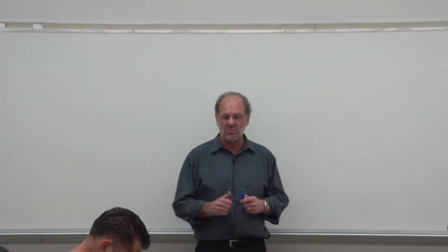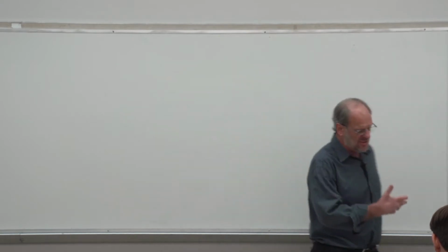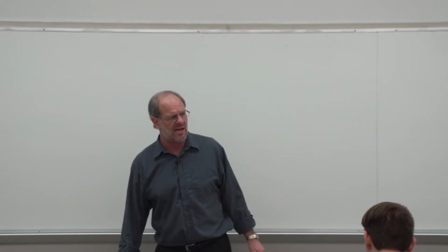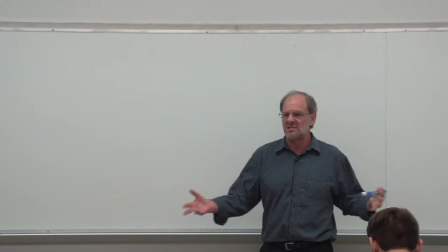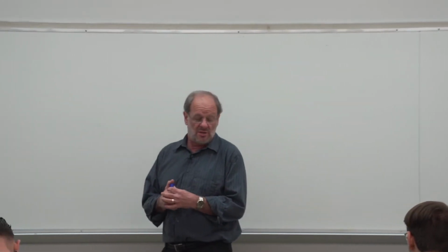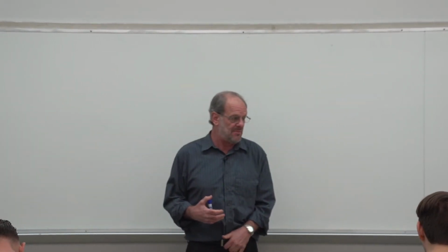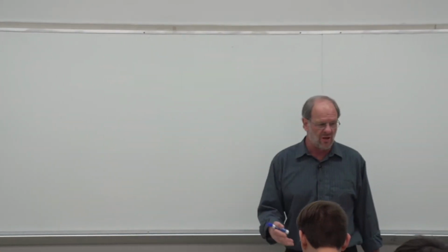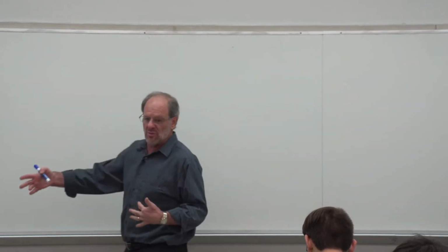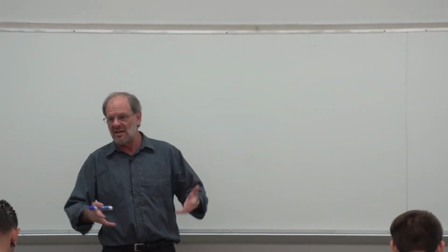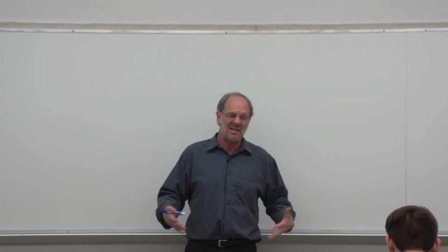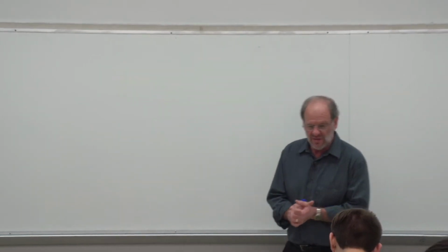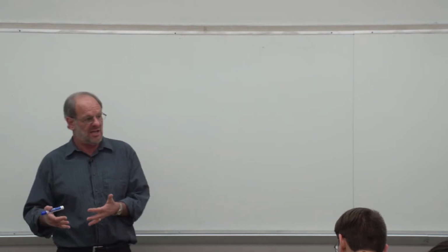Now, last time I derived some basic relationships, which are called the Maxwell relations. Following that, I went through just one analysis that I called the bounding analysis that allows you to essentially verify that the Maxwell relation works, that is a valid relationship. If one were to have solved that example problem out in the real world, not as an example, but a real world problem, well, then you're not going to have thermodynamic property tables. You would actually be taking data, right? Temperature data, pressure data, volume data, mass data, and then using those various differential relationships generate the unknowns.